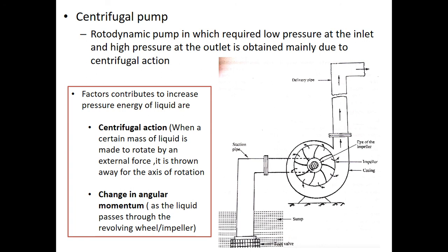For example, when a mass of liquid is allowed to rotate by an external force, it is thrown away from the axis of rotation and a centrifugal head is obtained which enables the liquid to rise to a higher level. So that is how things work here.